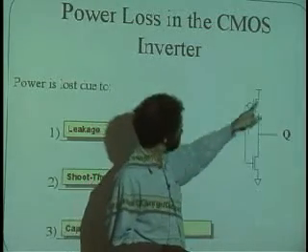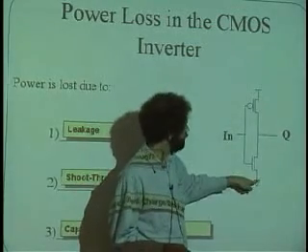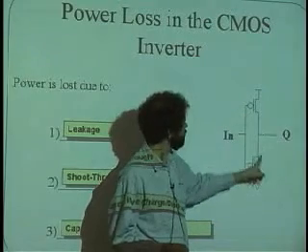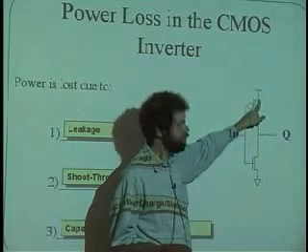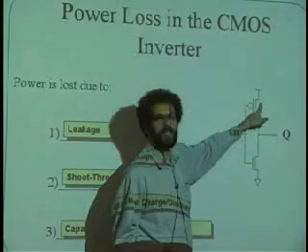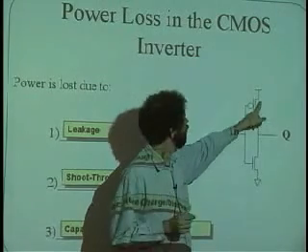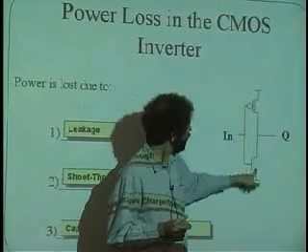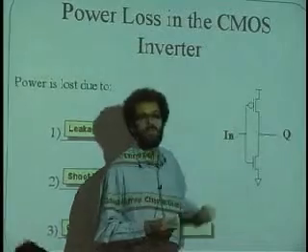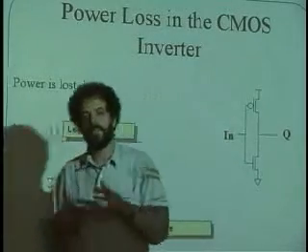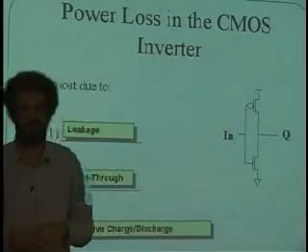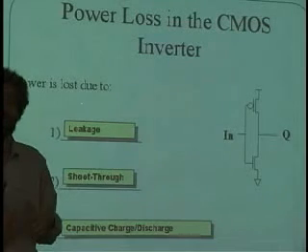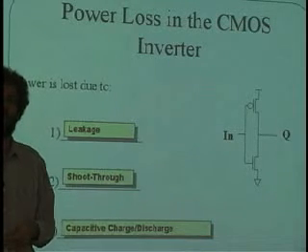And what that means is that here's high voltage and here's ground, that when this switch is off and this switch is on, a trickle amount of current, some femtoamps of current, very, very small, will trickle through here, and some current will go directly from the plus 5 volts to ground. And that current times whatever the voltage is on the power supply will equal power that turns into heat. Tiny, tiny amount of heat.